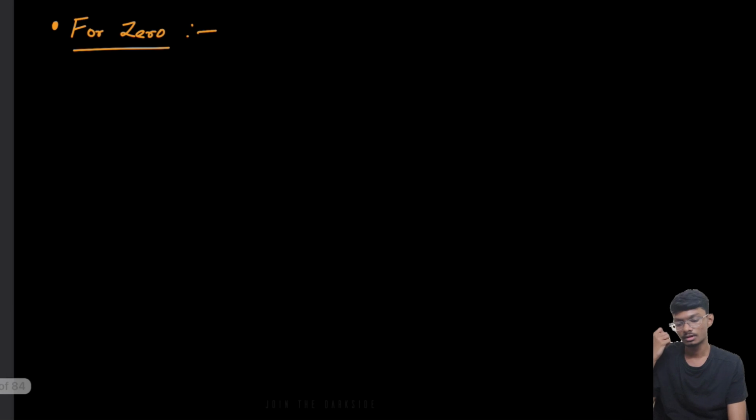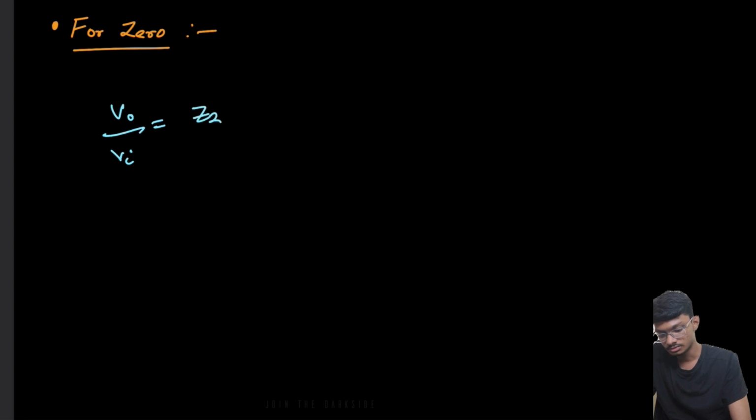Now let's see what a zero is and what a pole is. First, what is the definition of a zero? The definition of a zero is basically that the magnitude of the output voltage should be zero at a finite frequency, or at any frequency, for a finite value of input voltage. The input voltage should be finite. So how can we find the zero? V over Vi equals Z2 over Z1 plus Z2. How can we get zero for finite Vi? For finite Vi, if this goes to 0, then we'll get a 0.